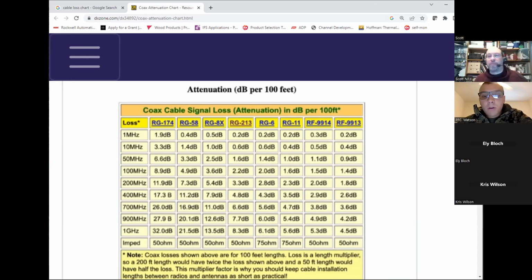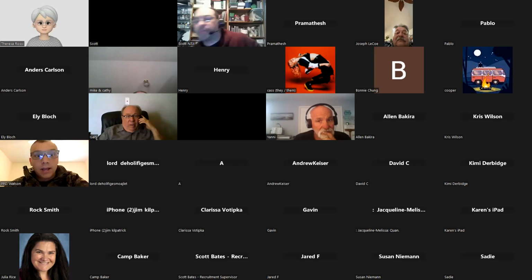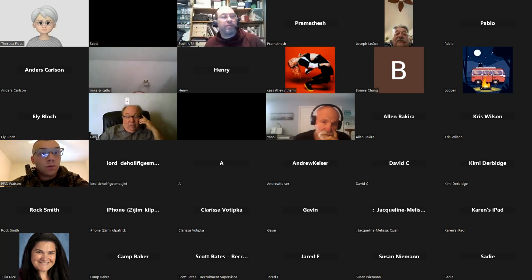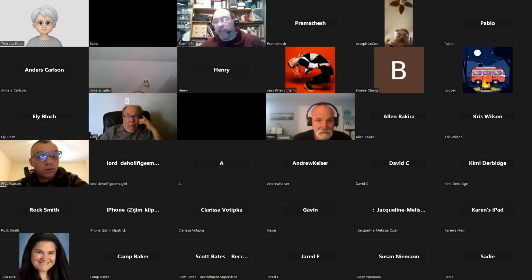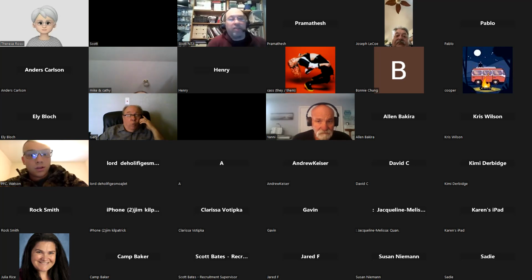So there was a problem on the technician level quiz: what is the decibel change from 10 to 20 watts? That's still 3 decibels, because it's a doubling. It doesn't matter the number that you start off with, because it's a logarithmic scale. It's a ratio. If you go from 10 to 20, that's the same as going from 100 to 200. It's the same as going from 1 million to 2 million. That's pretty incredible to think about.